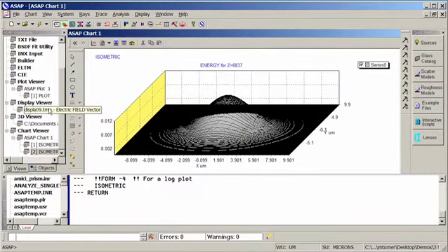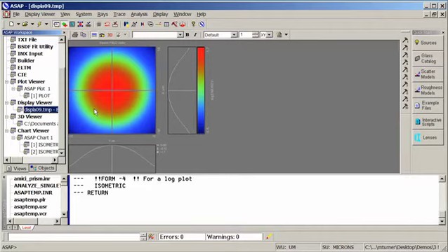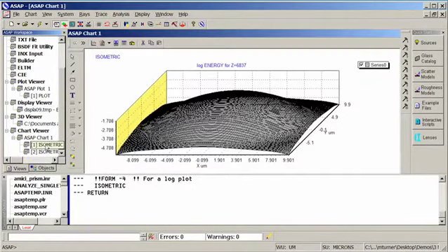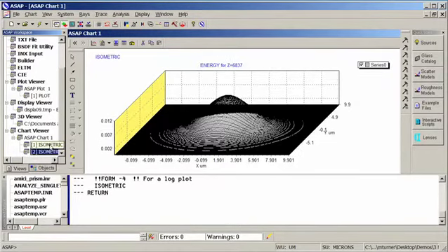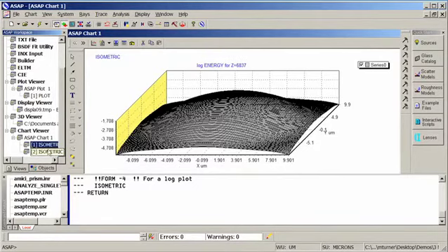In this particular case, we use Gaussian beam decomposition, and we defined our input electric field, and we can get information about the electric field as it leaves the second component. We can look at the three-dimensional false color plot or isometric information, and this is the information about the electric field at two different locations, the input and the output. From this, we can get information about the fiber coupling efficiency and the shape of the wavefront.